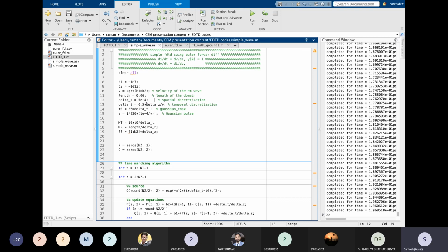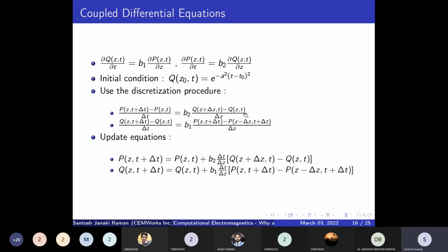Another thing here is that you can actually derive this. Eventually, these are differential equations, right? So you can write it in the form of a matrix, wherein x of n plus 1 equals A x of n, where A is a system matrix. For a continuous time system to be stable, the eigenvalues of the system matrix should always lie on the left-hand side of the S plane, right? And for a difference equation, the eigenvalues should lie within the unit circle.